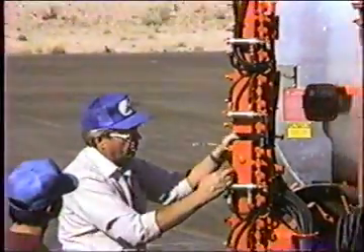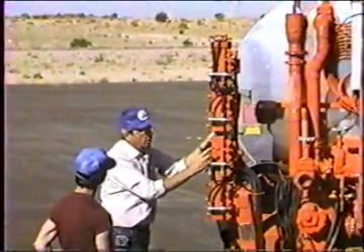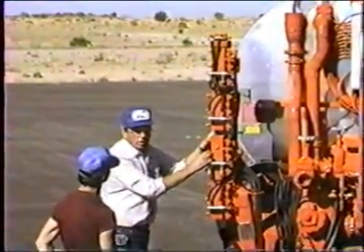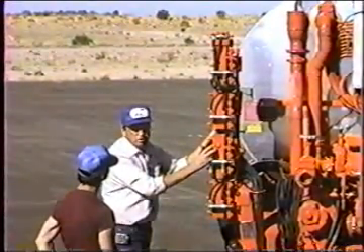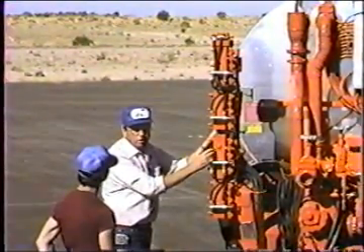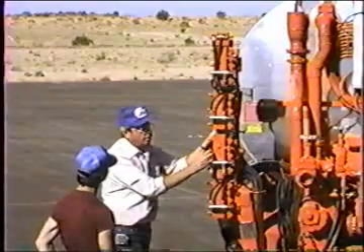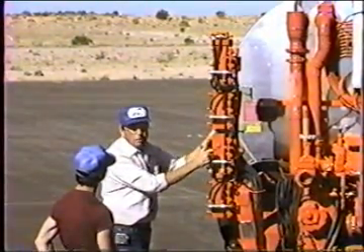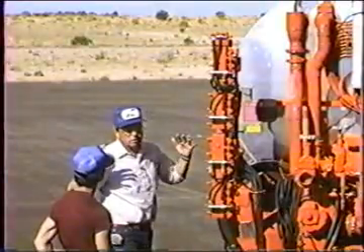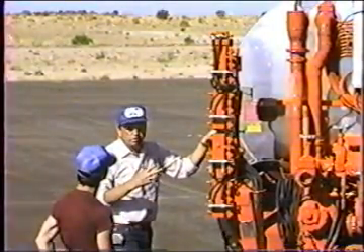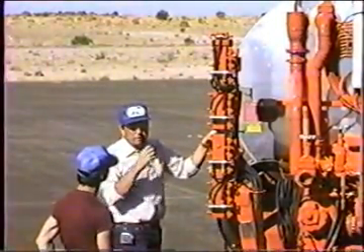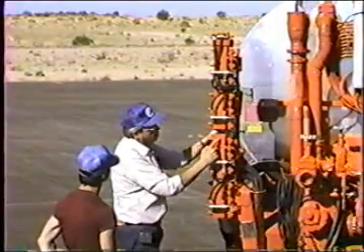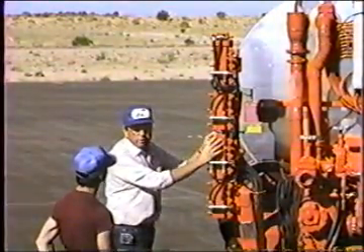Okay, with an enclosed nozzle valve such as this, we can circulate all day long paving grade asphalt, which is the hottest material. We can circulate that all day long in a 30-degree wind, and when we turn this spray bar on, we have instantaneous spray. There is never any drooling, never drip. We have instant spray, and that's the major advantage of the totally enclosed nozzle valve.